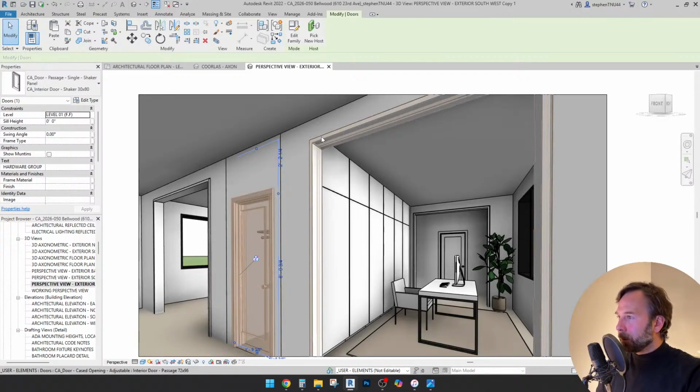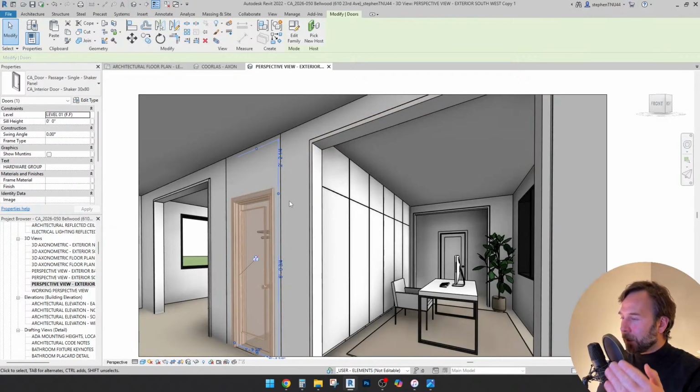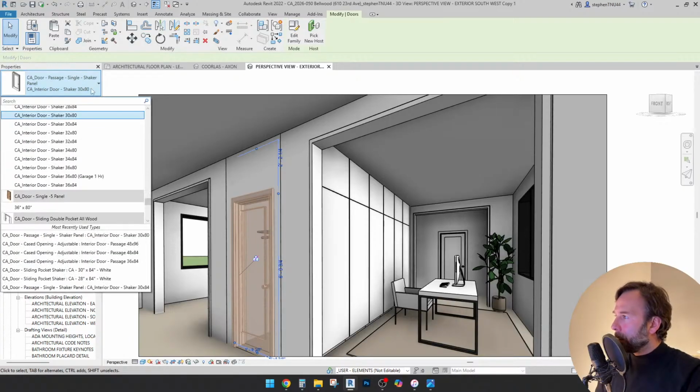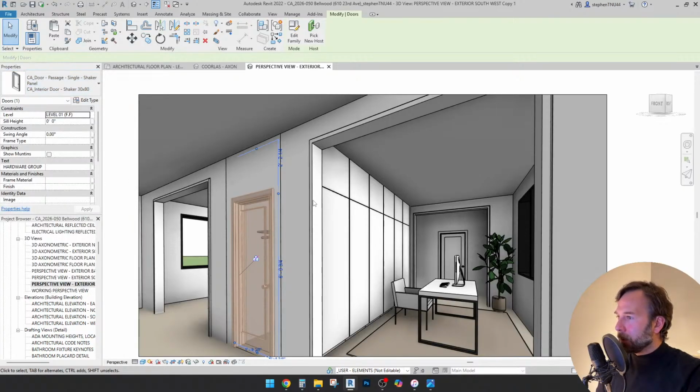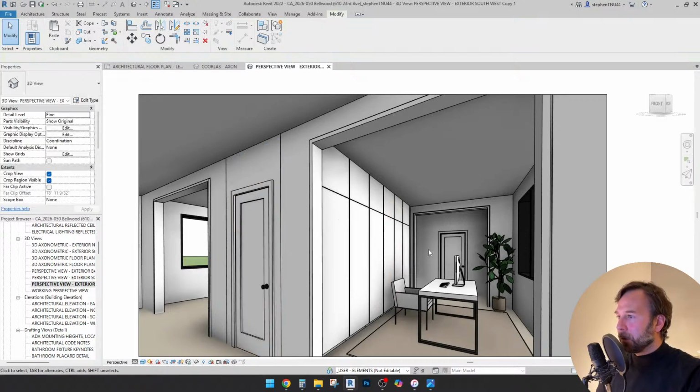This, we're not going to be able to get up to that height. We have the stair run conflicting on the inside of that closet anyway at some level, so I'm okay with leaving that as either a 7-foot or 6'8" door. I think we're going to propose that none of the doors are lower than 7 feet, just to keep most of the alignments the same. Hide these lines for now.